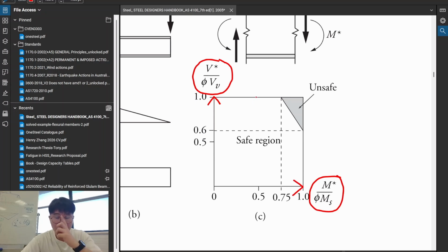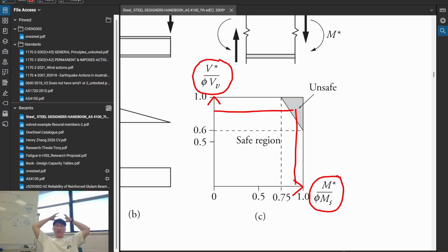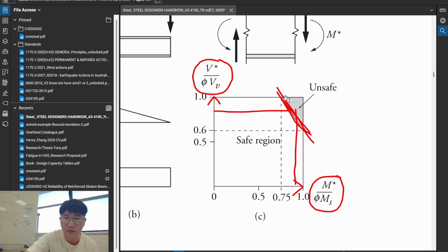Yeah, basically, if the damage is too high on both of them, even though they haven't individually failed, right? So say you're at like 90% damage for shear and 90% damage for bending, you're in the unsafe region. That's what it's trying to say. Do you know what I'm saying? Yeah. So this line here is what that formula that you saw before was, okay?